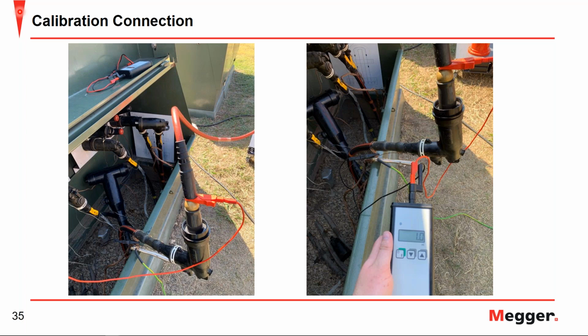And what I mean by that is, in cable, partial discharges are typically some hundreds of picocoulombs and maybe on the order of nanocoulombs. So 1 nanocoulomb is really the go-to for on-site testing, unless you experience higher noise, and I'll cover that in the instances going forward. But 1 nanocoulomb is typical for that. If you were doing rotating machines, it may be 5 or 10 nanocoulombs because those discharges are higher. So it just depends on your type of asset.